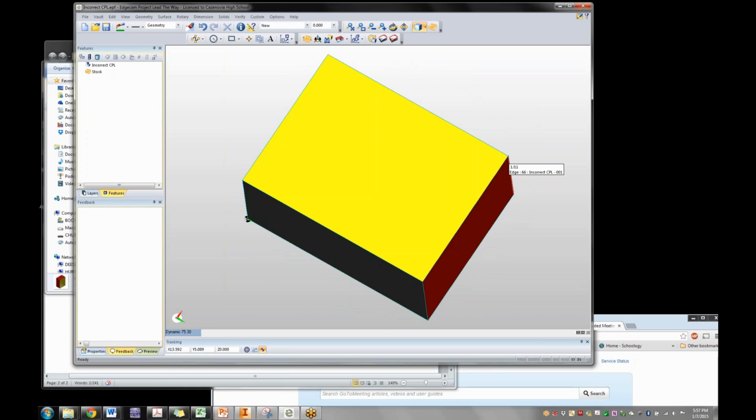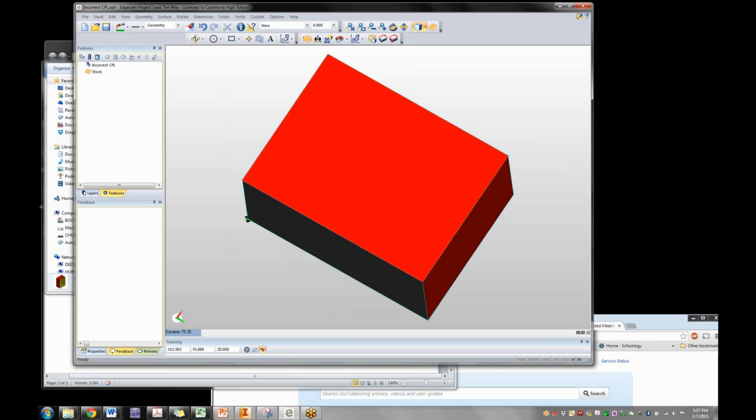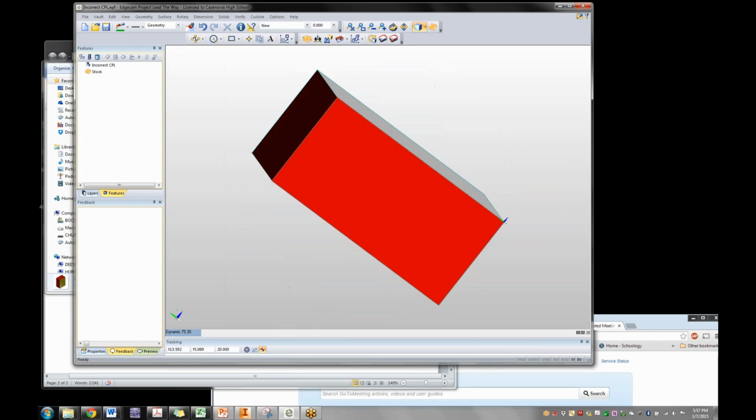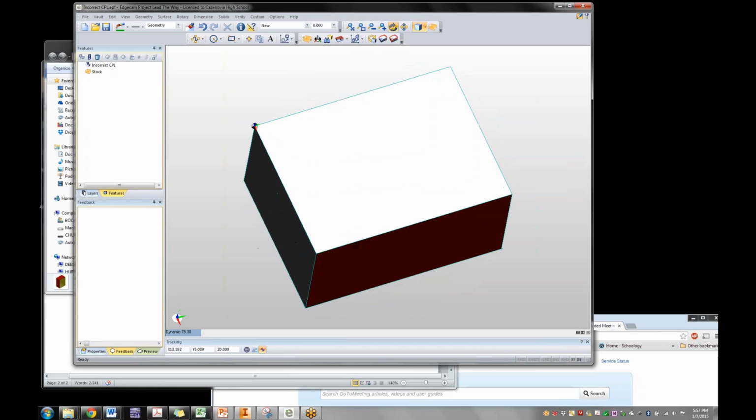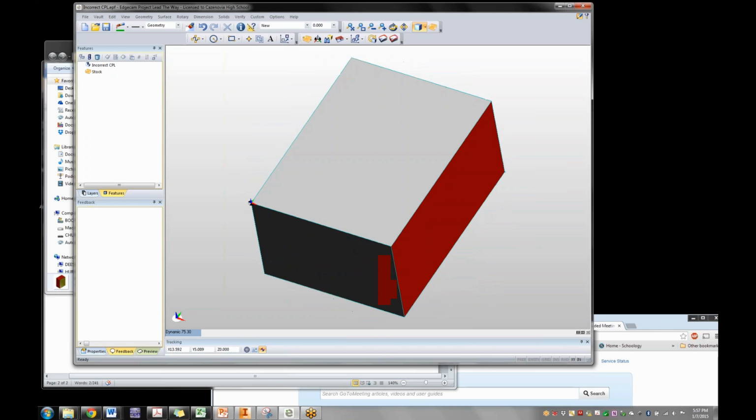And that's why your order of operations is so important. You need to do that auto stock first, especially if you're going to add stock. If you're going to add stock in the positive Z so that you can do a facing operation, you add the stock, get the positive Z, and then you're going to have to move the CPL anyways. So being able to move the CPL, even if you drew it right in Inventor, doesn't mean it's not commonly going to have to be moved.